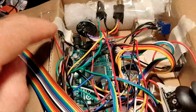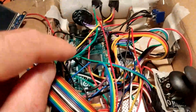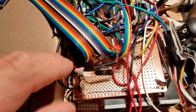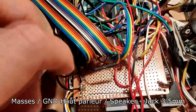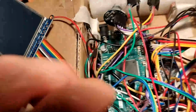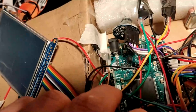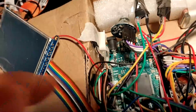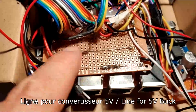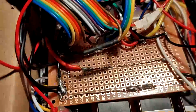So here I have the ground for the two jack connector going to my ground path, and I have another wire here which is going below to the ground plug of the Arduino. Don't forget to connect all the grounds of the circuit. So now I'm gonna connect all the 5 volts buck powered supply modules on this new path on the PCB.